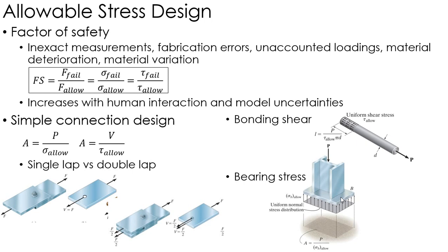So again, the whole idea behind this is figure out what your allowable stress is, and then design your system so that the area is large enough that it can support the load and keep the stress below that allowable stress that you have there.